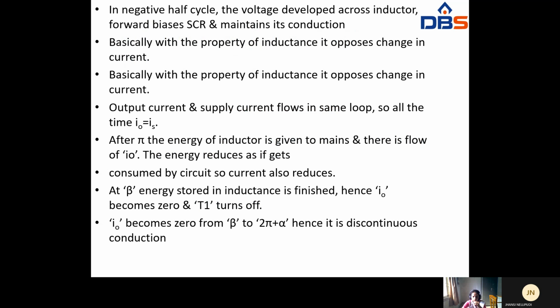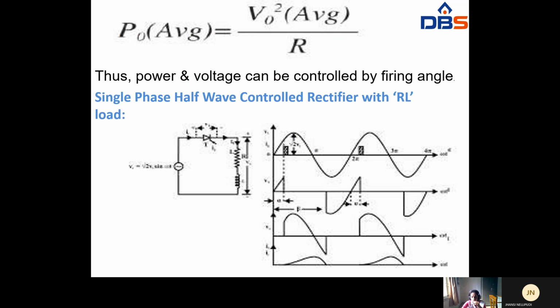So in these waveforms we have to see here that from 5 it will come to 0, and here, due to inductance, some amount of voltage will be there and current also will be there. Okay. So here this is the inductive conduction state. So when you are taking this beta, it is from pi to beta, or 2 pi to beta. Okay, this is the inductance conduction state.